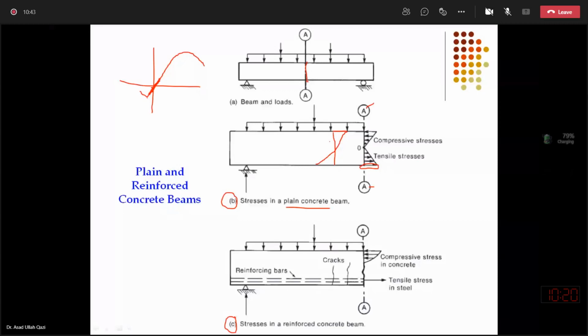I will go through some assumptions on the next slide, where we will talk about the strain and stress diagrams. So in terms of plain concrete without reinforcement in a very low stress range at the midspan section, you can imagine that these may be the stresses when the beam is subjected to hardly its self weight. Very low bending stresses are present. Still you have almost a straight line, and the same you can say C is equal to T, and the beam